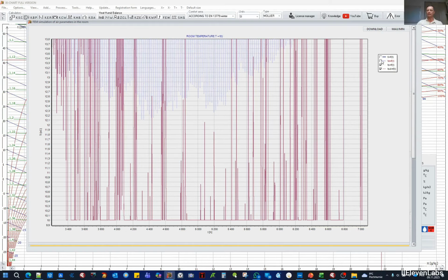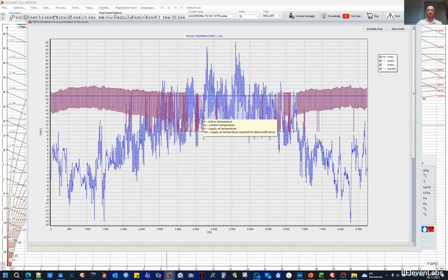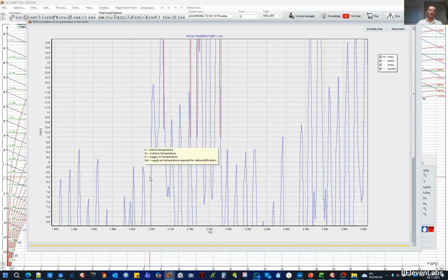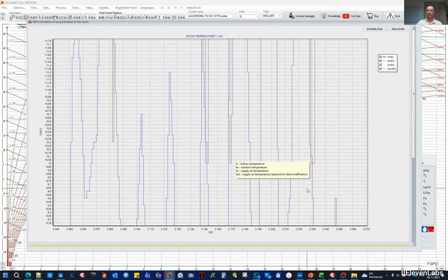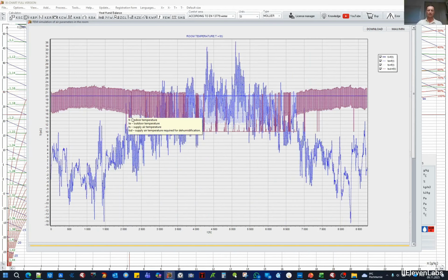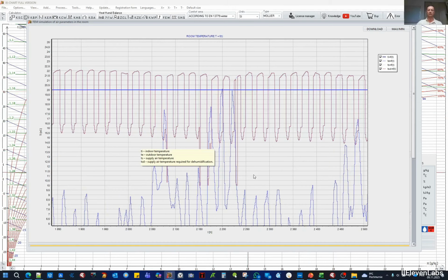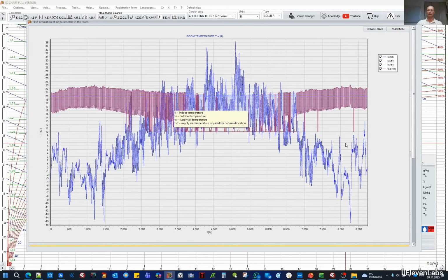And the strength of these simulations lies in the fact that on the Molière chart, on the psychrometric chart, we usually only analyze the extreme parameters of the outside air and do not see the whole picture of the situation. And I personally have made this kind of mistake a few times, not fully realizing that drying would be needed, for example, at the turn of March or April, and then those parameters might not be maintained, which really has a decisive impact in some rooms.